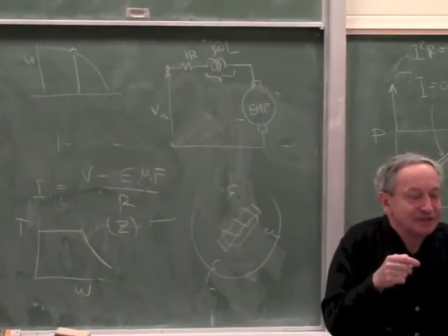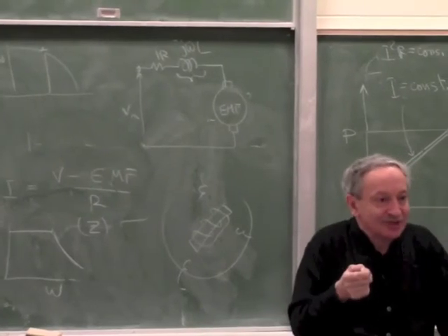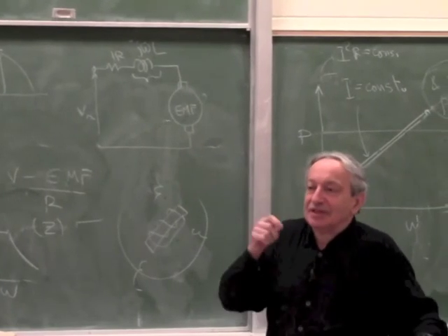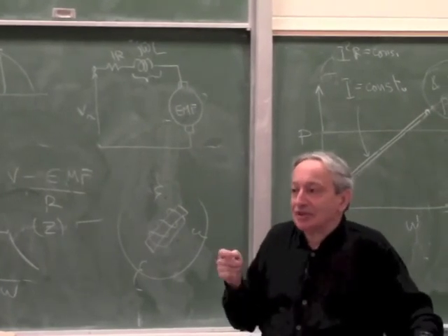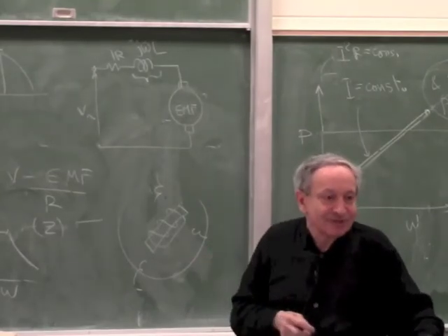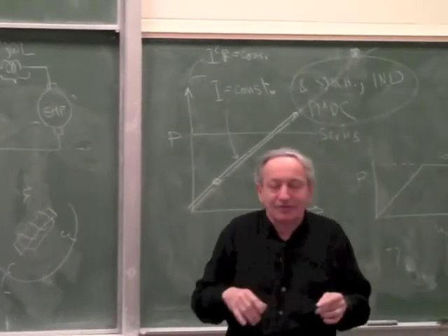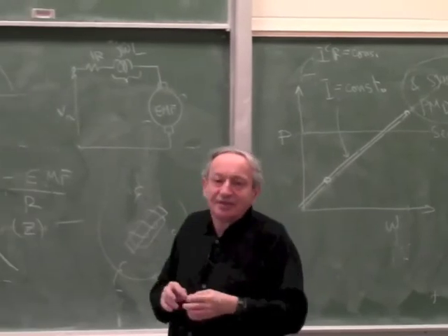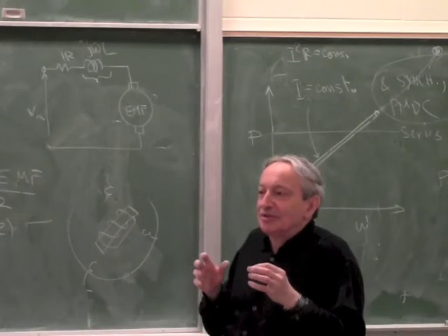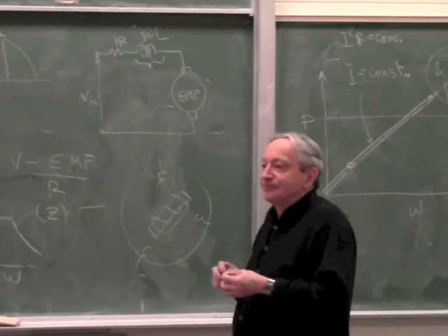Now if you have fewer turns, you can use a thicker wire. If you use a thicker wire, it has more torque. So the power of the motor doesn't change. If you make a motor with fewer turns, heavier wire, it has less voltage, okay, but more torque. So the torque times the RPM is constant. So you can gain some power by running the motor faster in a smaller package, but in general, very crudely speaking, the power doesn't change very much. You can play around with the current and the voltage on the coils.